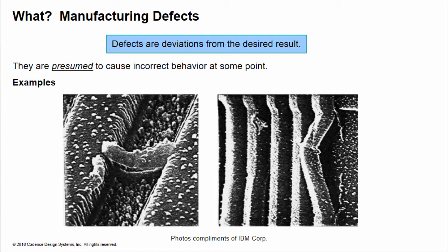For example, in the picture on the left there is some extra metal shorting two metal traces. In the picture on the right, a metal trace has become detached from the substrate and buckled. If the buckled trace is not touching the other trace, there may not be a functional error. But do you want to ship it? Will later mechanical vibrations cause it to either short to its neighbor, or might it break off and create an open? There is damage in a line across a number of traces, so there is more going on here than that simplistic analysis would suggest.